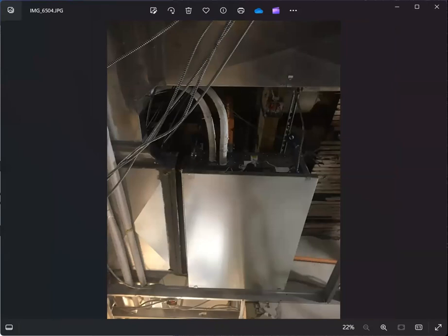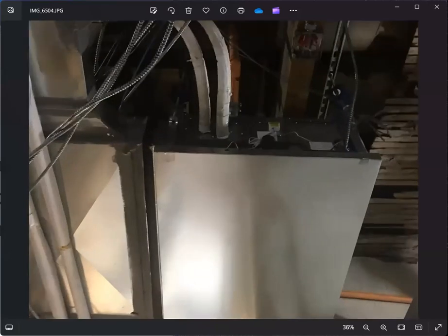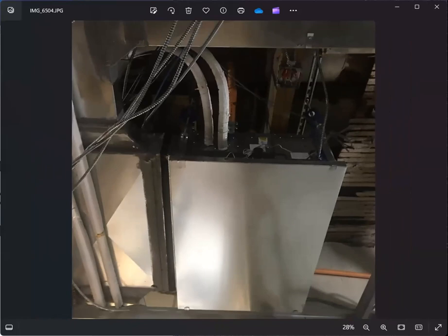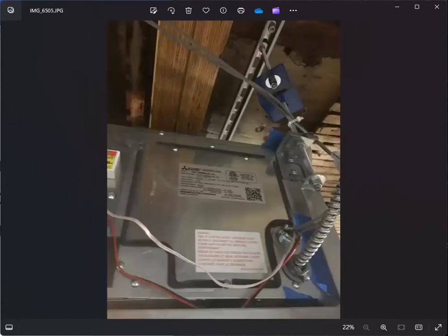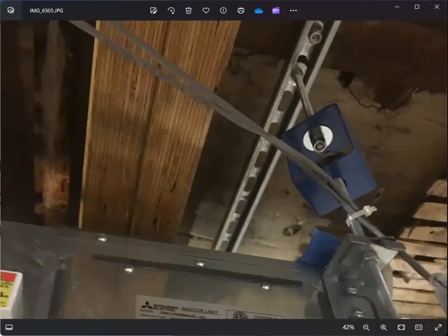This is another AC unit. So it has the drip pan. That's a precaution for the unit to prevent condensate from dripping. This drip pan usually has a condensate pump on the top to suck the water that will condensate, to prevent it from building up inside the ceiling of the house. And this is the vibration isolator that I'm talking about.